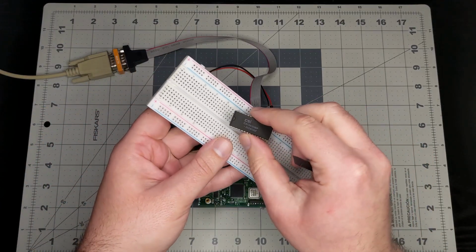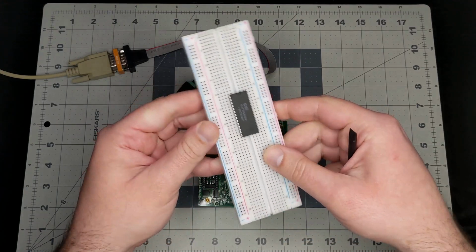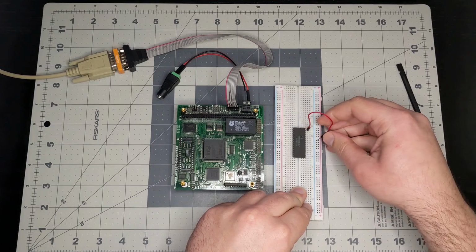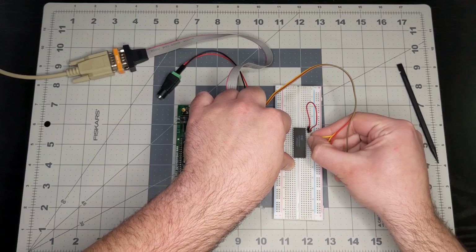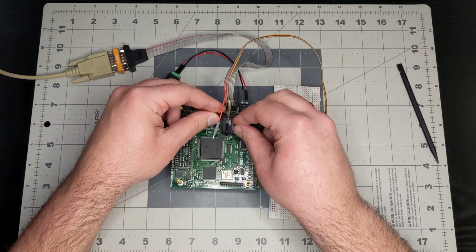To make things even more fun, we're going to cram our recovery tool into this 8 kilobyte EEPROM, as it was the only non-volatile memory device I had when I first did this. These are accessed just like the onboard flash memory. They have 8 data pins to output the byte at whatever address is selected by the address pins. And in this case, there's only 13 of them, as this is an 8 kilobyte memory. 2 to the 13th power is 8,192. So we'll connect the write enable pin to VCC to disable writing, the output enable pin to the expansion connector's memory read pin, and the chip select pin to the UCS pin.